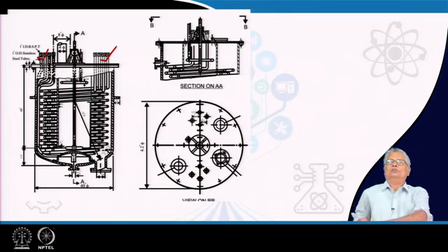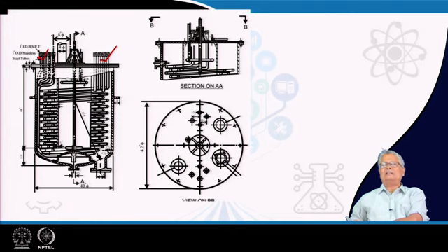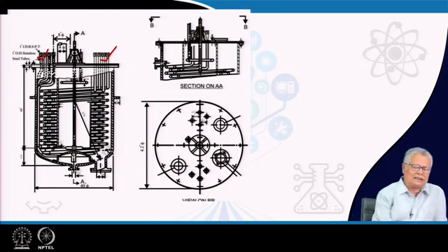Once you have found out the amount of hold up in your reactor and the dimensions of your reactor, so that you have all your tubes submerged, it will be possible for you to refer to the basic design of the impellers for stirring in one of your earlier classes and design your stirrer and its power requirement.